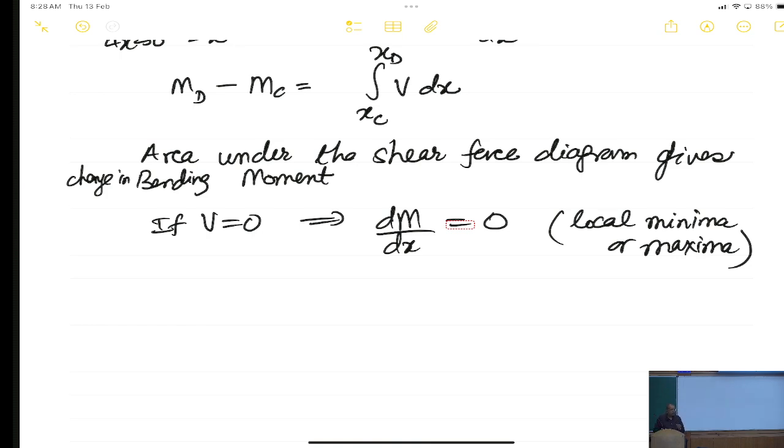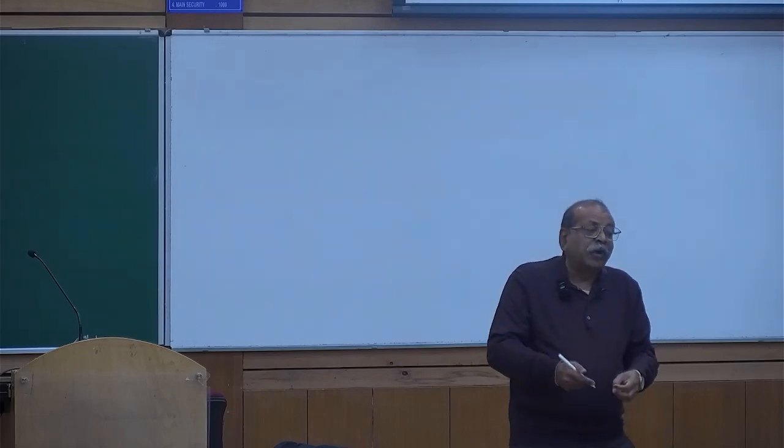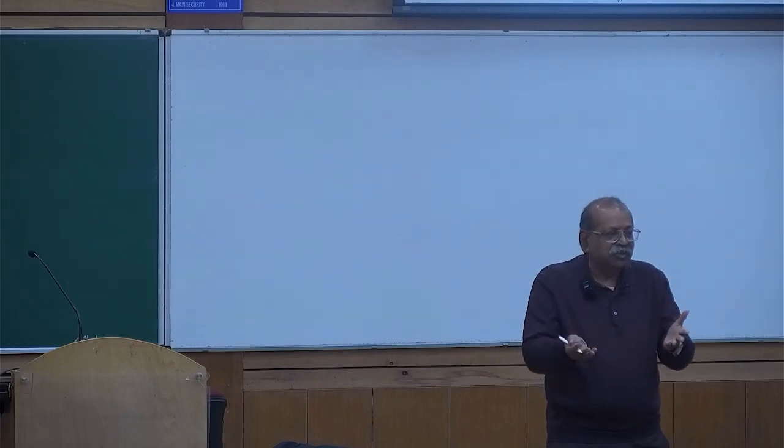And actually, when we are doing solid mechanics, what are we trying to find from the shear force and bending moment diagram? The maximum magnitude of M. So, it will be either the minimum or the maximum, the absolute M, wherever that is maximum, that is the M we have to use to find the maximum bending stress.